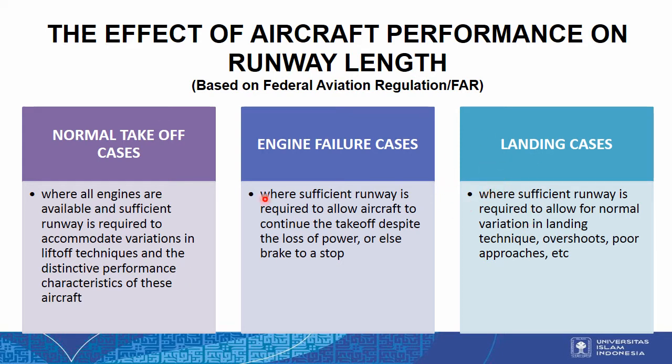So how about piston aircraft? For piston aircraft, the criteria are like the above, but the first criterion, the normal takeoff case, is not used. Why? Because in piston aircraft, engine failure occurs more commonly than in turbine aircraft.